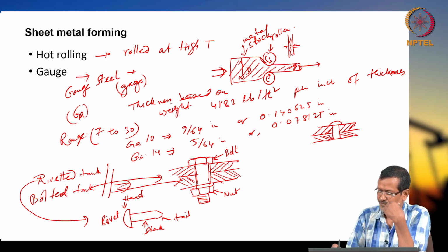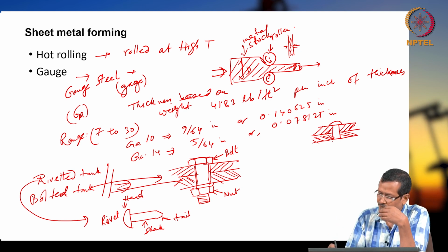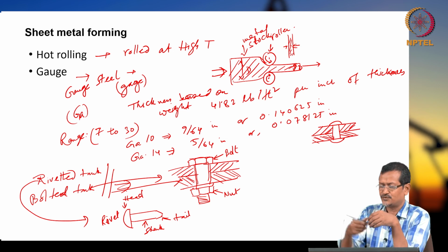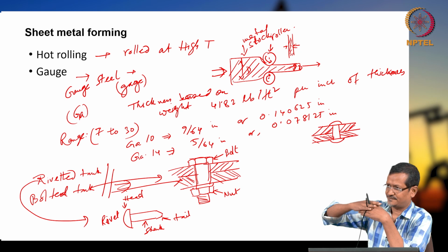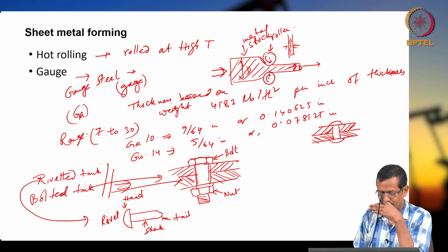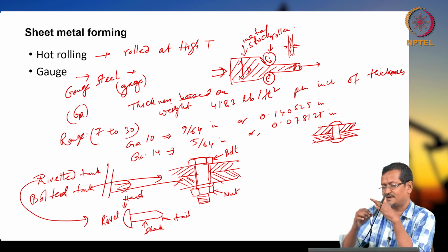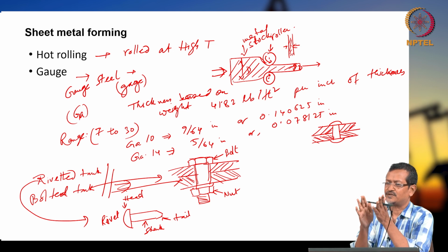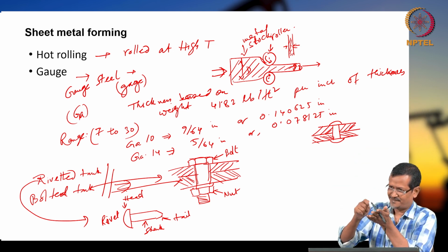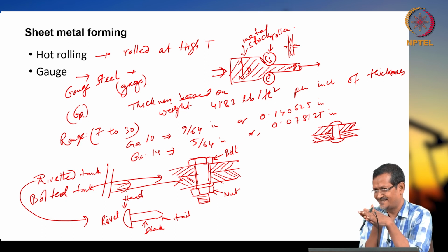That is why I am putting different angles, you can see one will be around 40 degrees, one will be 135 degrees, and this one also like this. What you do, let us say this one is my rivet, one metal is there, you made a hole, another metal is here. One rivet, you see this rivet head is there. One part is already curved, another part is like a pin, the shank is here, my tail is here. What you do, you use one very big hammer and make this one also curved. Okay. So, this will be a permanent joint.